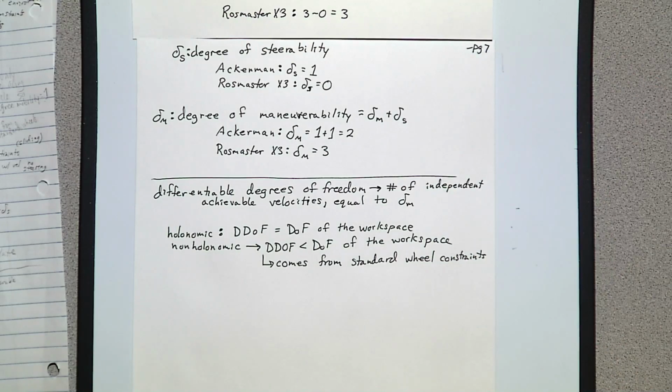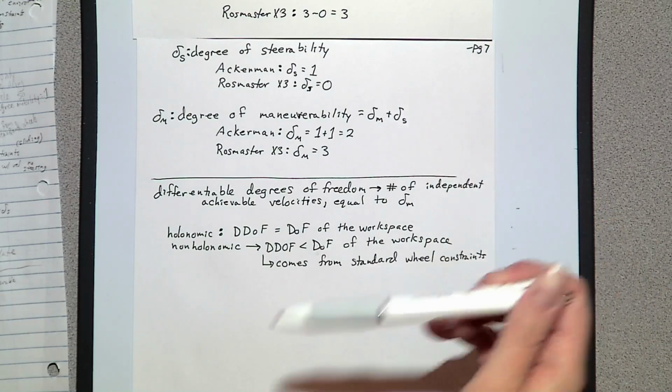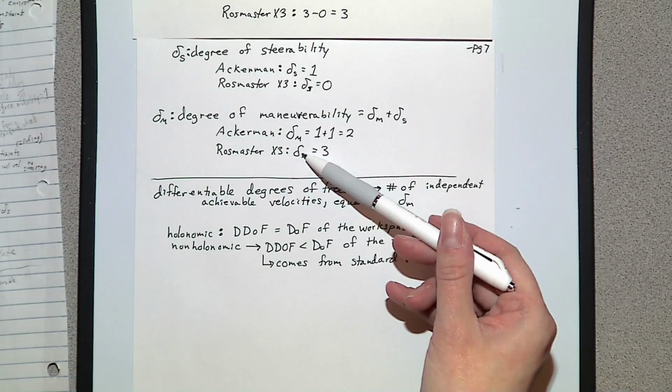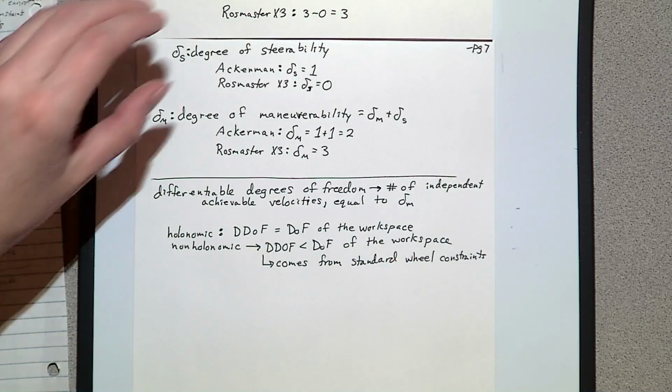So it comes down to a trade-off between the maneuverability and the stability. As we talked about before, if you have the Mecanum type wheels and say you want to do a fast turn, you're going to get a lot more sliding than you are with an Ackermann type, and you're also going to have a lot more slippage. So estimating where you are based on odometry data alone is more difficult for an omnidirectional robot versus an Ackermann. So a little bit of trade-off depending on what emphasis you want to put on for whatever your application is.